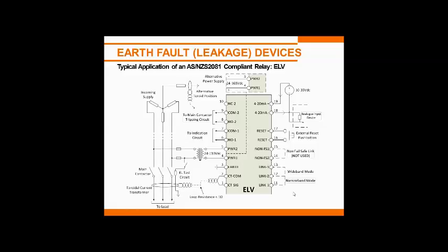And as I mentioned before, the ELV has a number of bands. It has 3 bands. It has a narrow band if you link 11 to 12, so that's 50 hertz only. This is a frequency band. A wide band if you link 1 to 3. You're then measuring 0 to 10 kilohertz, or a few hertz to 10 kilohertz. It also has a weighted band, which is linked 1 to 3 or leaving the links off altogether, and that gives you both a wide bandwidth but with a reduced sensitivity at high frequency. This stops any unwanted trips. It still gives a safe system, and if you want to know more about that, the manual explains that fairly well.